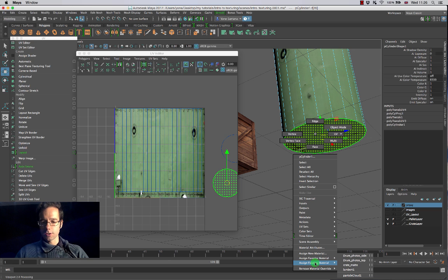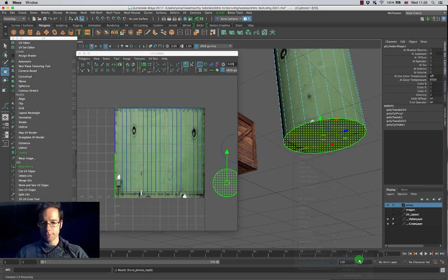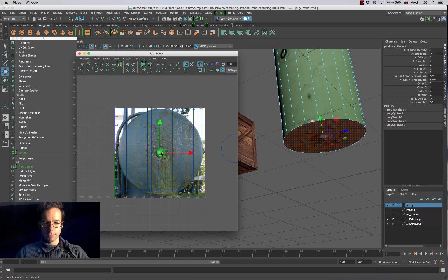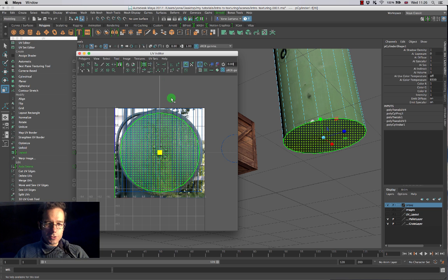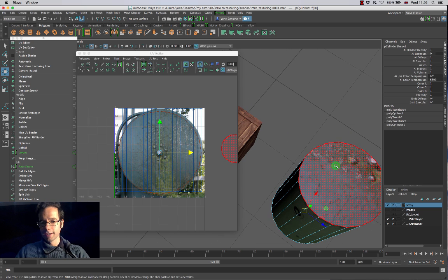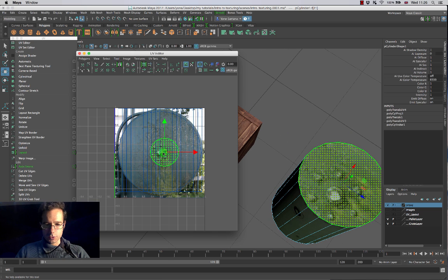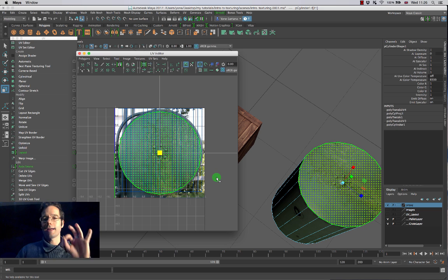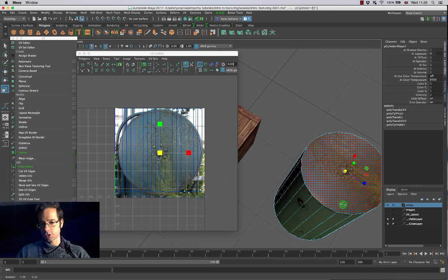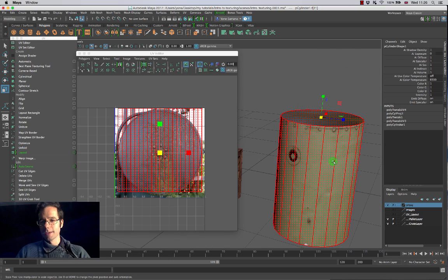And I can come over here into Assign Existing Material, Top, and you're going to see that it's going to project this over here. So now I can come into the image, put it in the middle of my scene, switch using the keyboard shortcut R to bring up the scale tool, and then I'm just going to scale this up like that. Maybe reposition it a little bit. I'm just keeping it in my view over here. And again, you can see that this isn't the best texture in the world because I'm not doing any Photoshop work at this minute. I'm going to show you guys how to do some Photoshop work to actually improve your textures in just a second.